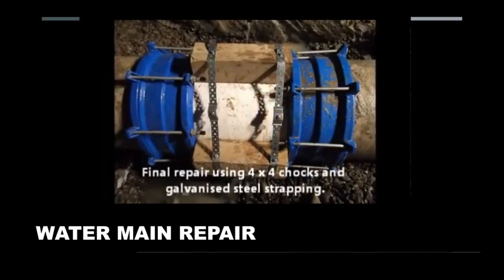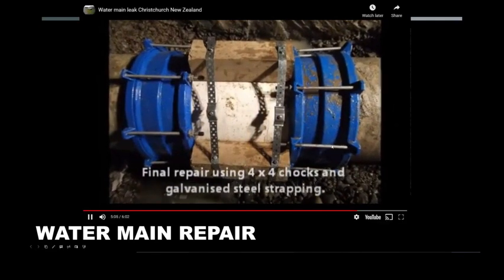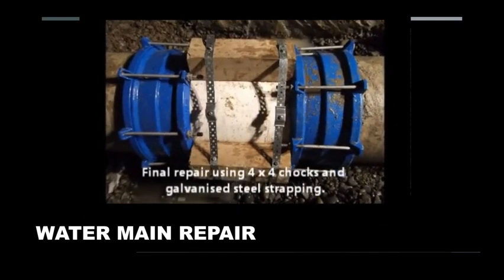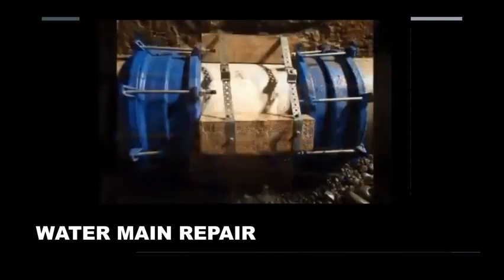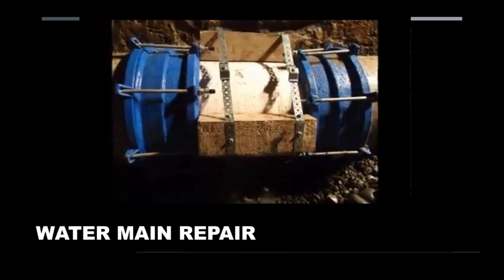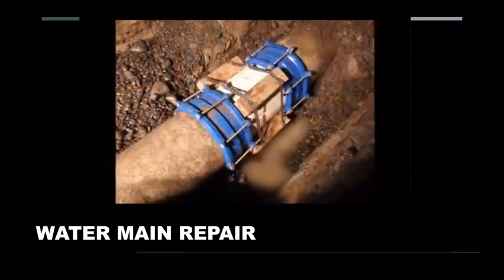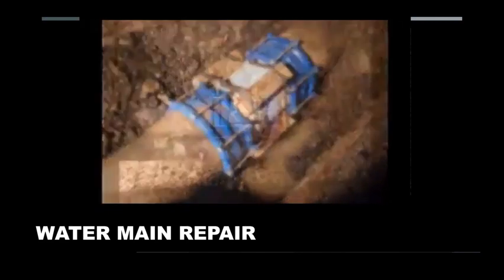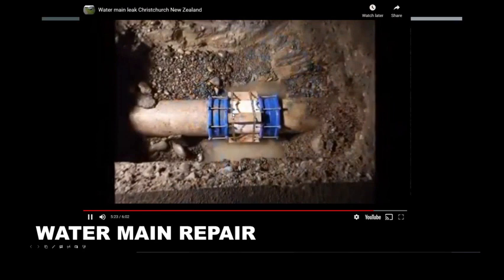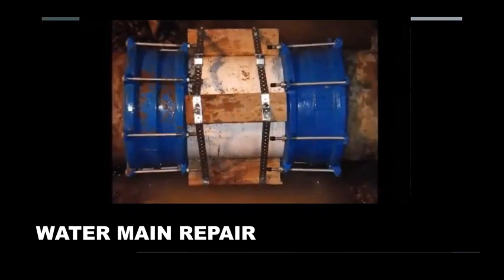So this time they chocked them apart with some timber and used some galv strapping to hold it. Although seeing the original galv bolts corroded away to nothing, I don't know how long that will last, but I guess it's better than nothing. The gravel might help hold the chocks in position anyway. Probably a big bolt that went right through both with a back nut would have been better, but I didn't think of that. Might have been hard to line them up.